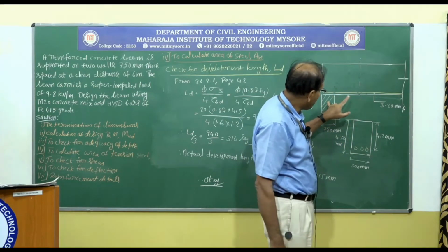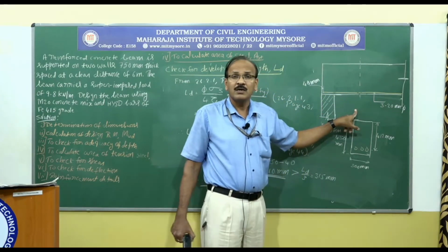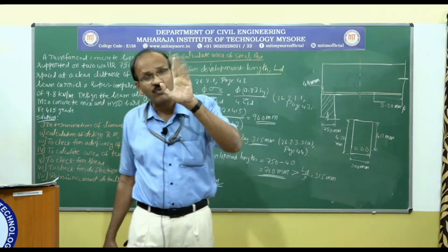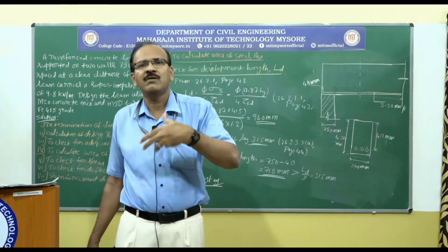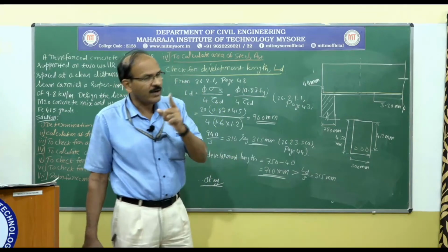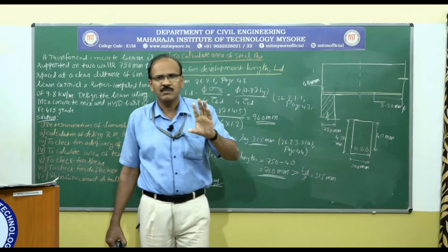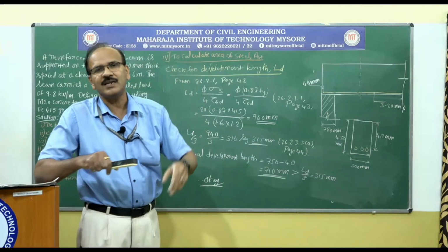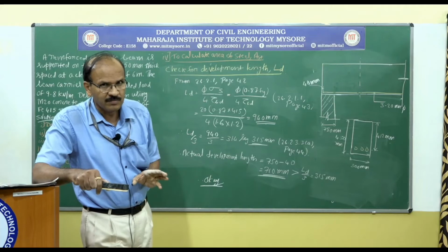Once you find out where you can cut that 1 bar, from there you extend that for a distance equal to 12 times the diameter of the bar or 1 effective depth. So this requires a little bit of calculation. By keeping that in mind, what I have done is I have ignored it, and instead I have continued all the 3 bars into the support. So that way I am using a little bit of extra steel. Is it clear to you?